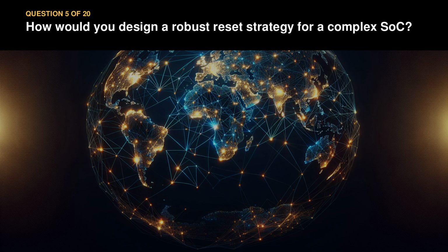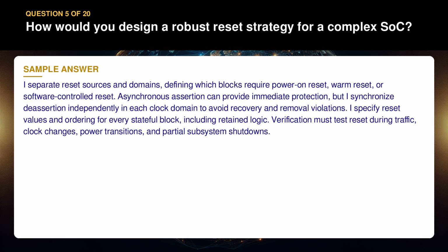Question 5. How would you design a robust reset strategy for a complex SoC? I separate reset sources and domains, defining which blocks require power-on reset, warm reset, or software-controlled reset. Asynchronous assertion can provide immediate protection, but I synchronize deassertion independently in each clock domain to avoid recovery and removal violations. I specify reset values and ordering for every stateful block, including retained logic.